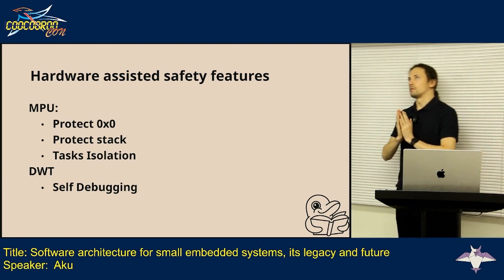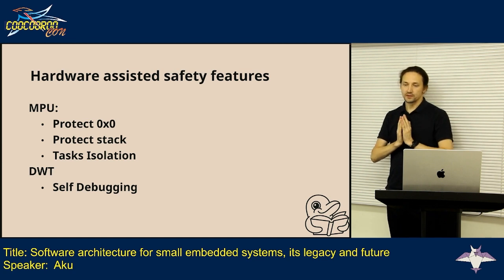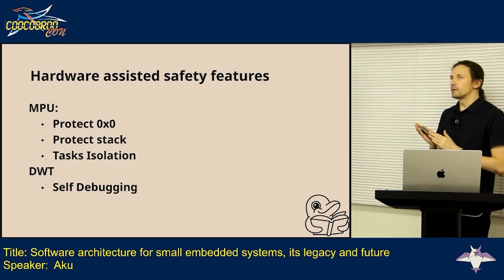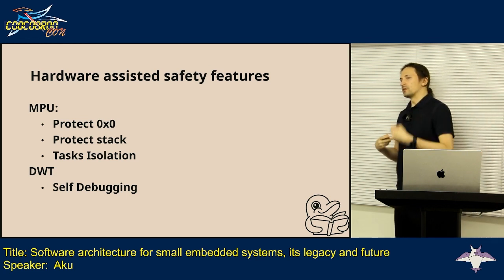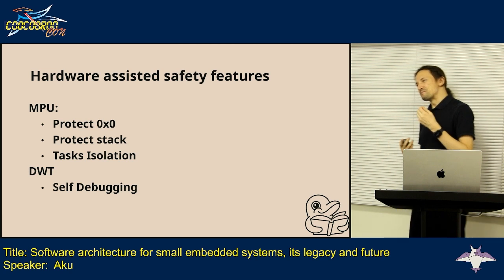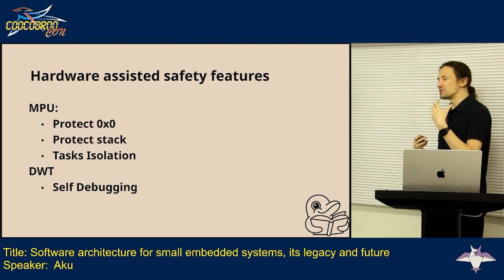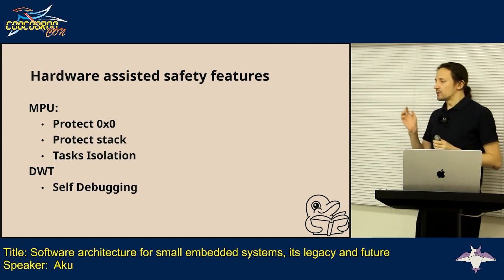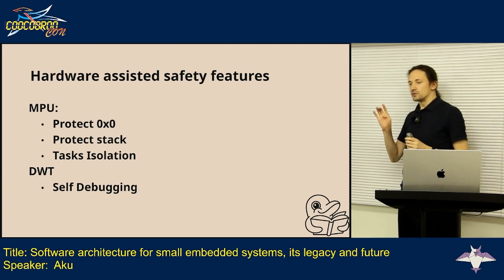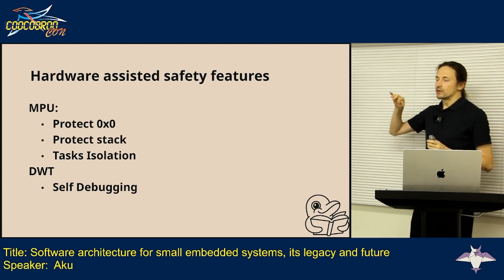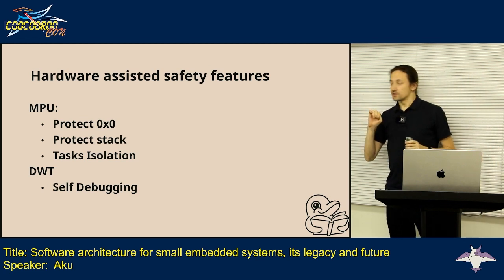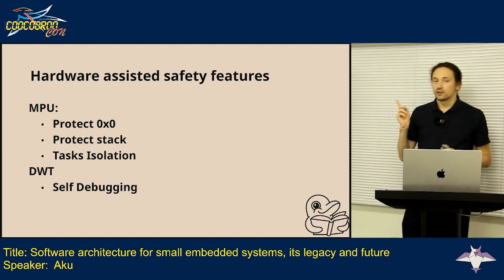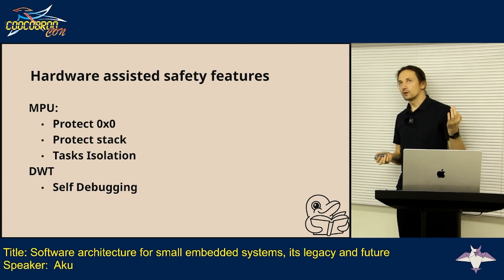And then, since debugging of hardware is actually quite complex, in some cases you may find that you just cannot use your debugger, you just cannot design a script with your debugger to catch some specific things. Like, for example, you do dynamic memory allocation, and then you do something with this memory, and then someone corrupts this memory, and you don't know who exactly is corrupting it. That's where you can use another thing called DWT in ARM cores. It's a debug, watchpoint, and trace subsystem.